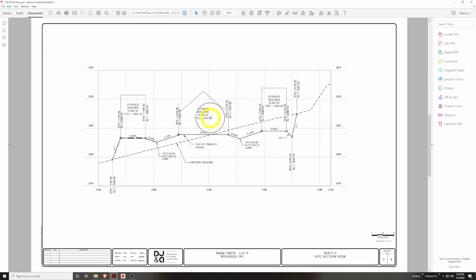So this is kind of just another visual of a balanced-ish site, showing equal amounts of cut and fill on a whole cross section across the site here. And really, if I really wanted to circle it with a pen, this whole area here is a big fill area because my design ground is above my cut. This area here is a big cut area.